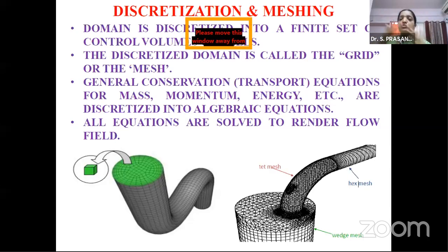There are many papers which discuss the skewness ratio, which gives you the statistics of the number of nodes, number of elements, and all these things. So meshing is a very, very important criterion next to geometry generation. I just want to tell you one point about geometry: even in AutoCAD you will experience that the edges have to properly coincide. Even if you have a small gap, the geometry that you have created in ANSYS will not be properly imported into your meshing module.